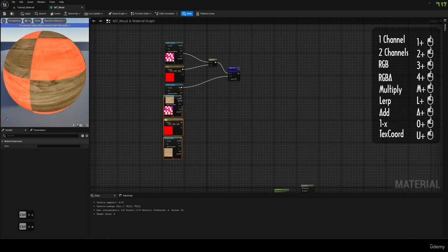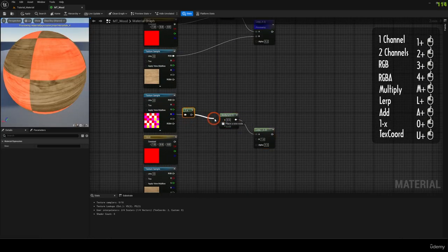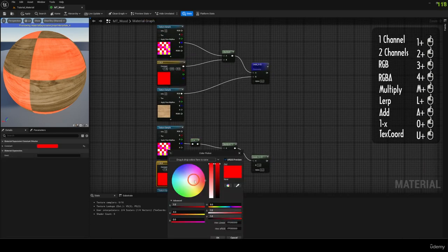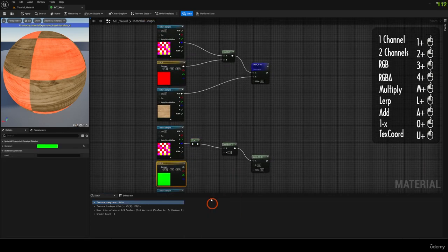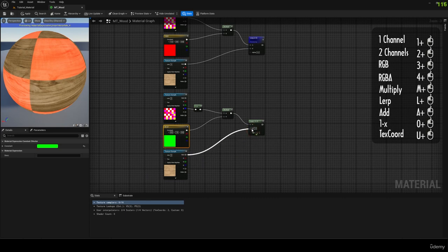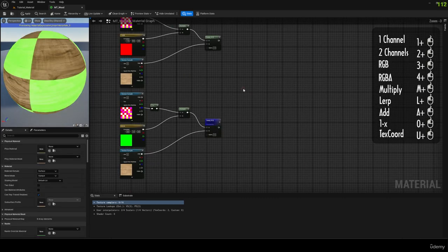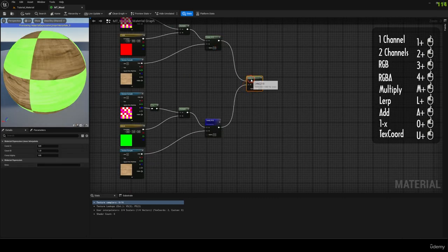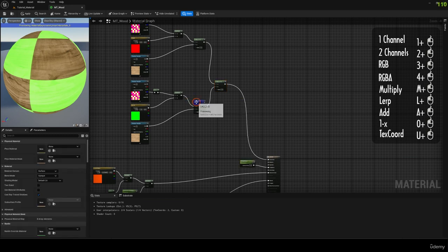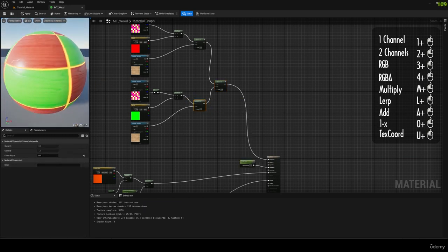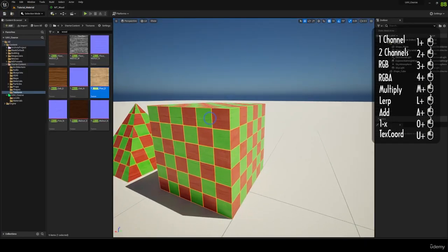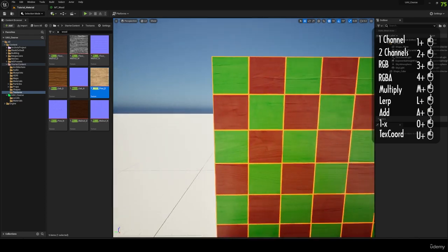We will apply the same process to the remaining tiles by inverting our blue channel with the 1- command. After obtaining the new green painted texture, let's create another lerp command to mix the 2 textures equally and obtain our painted material. We can display this texture by connecting it to base color.